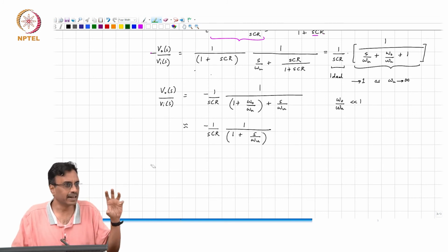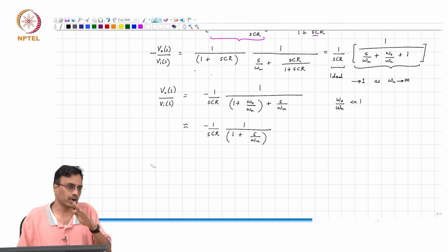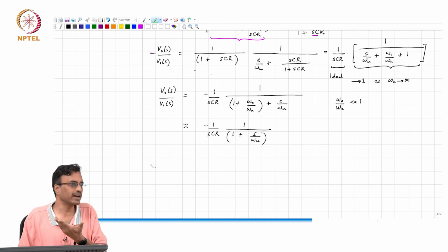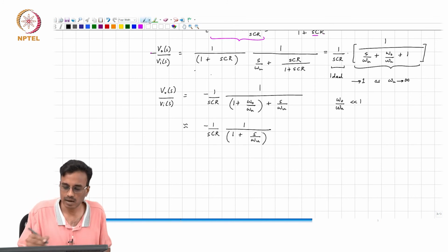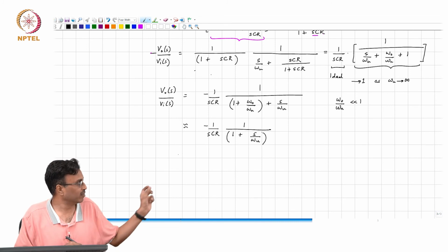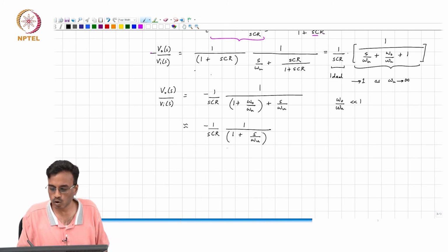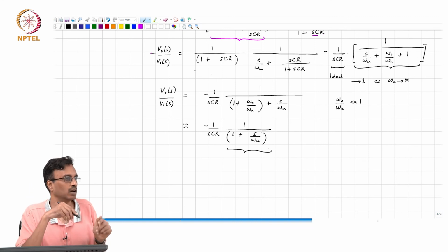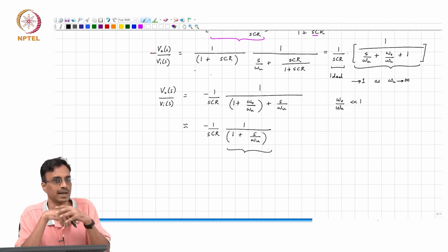If you had an ideal integrator, if you put a step, what kind of transient will you get at the output? You will get a ramp, alright. Now, if you have an integrator like this, where it has got some integration, but it's also got an extra pole, right, what comment can you make about the output response when you put in a step?